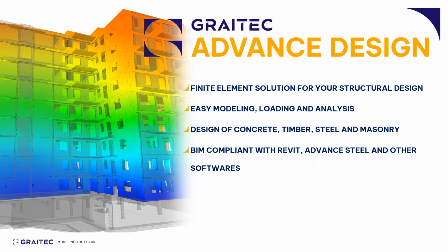After you've done your static calculation analysis, you can design concrete, timber, steel, and starting with the new version also masonry elements using national annexes to Eurocode or North American codes. What's most important, it's a BIM compliant solution, so you can link it with Revit, with Advanced Steel, but also any other software using open formats such as IFC.